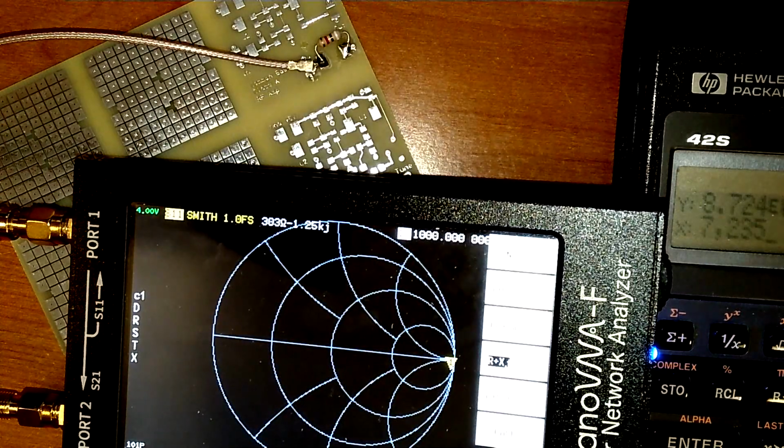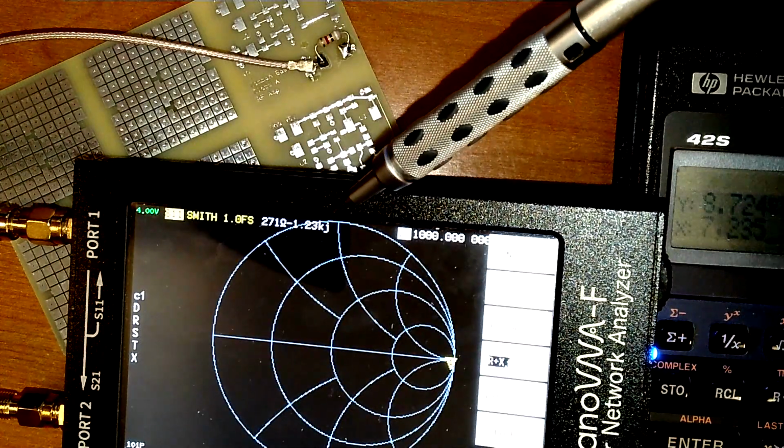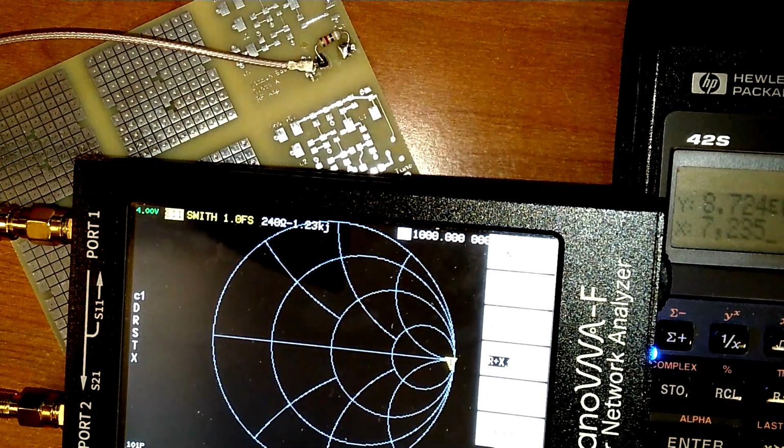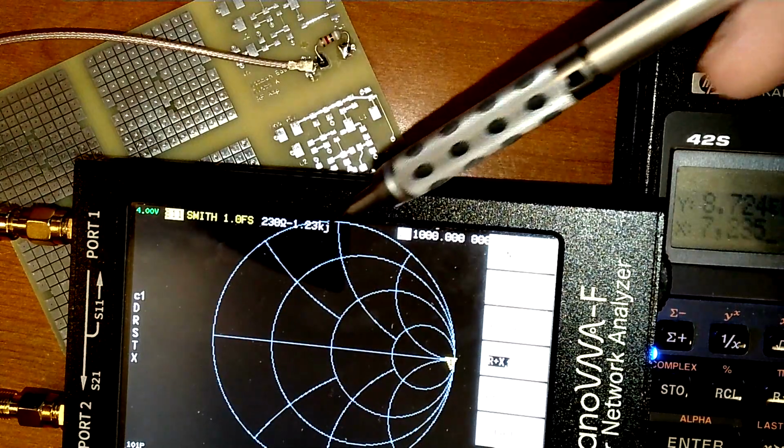But that's in parallel with about 1.2 k ohms of reactance. And so the net impedance is lower than either one of those two values. So for the 9100 ohm resistor, the total impedance is much less than 9100 ohms. It's somewhere around 1 k ohms.